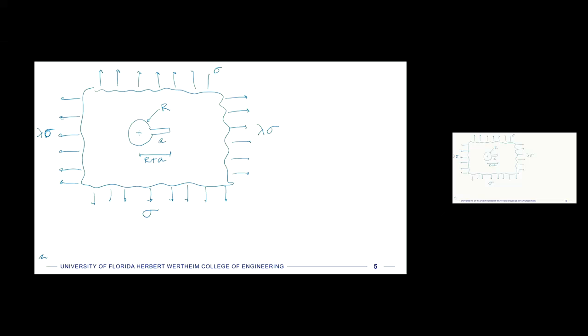So if we want to think about what is the mode and what's the stress on this, if we think about mode 1, then it's really only in the direction of this sigma here. So we can say that for mode 1, if there's a tensile stress, the K1 is equal to that C1 times the stress only in that direction times the square root of pi a. Right? So it really does simplify down quite a bit.